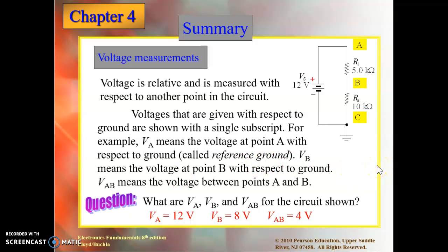Voltage measurements. Voltage is relative and is measured with respect to another point in the circuit. So it is very important to keep track of what it is that we are measuring, because voltage doesn't mean anything if we don't have a point of reference. Voltages given with respect to ground are shown with a single subscript.